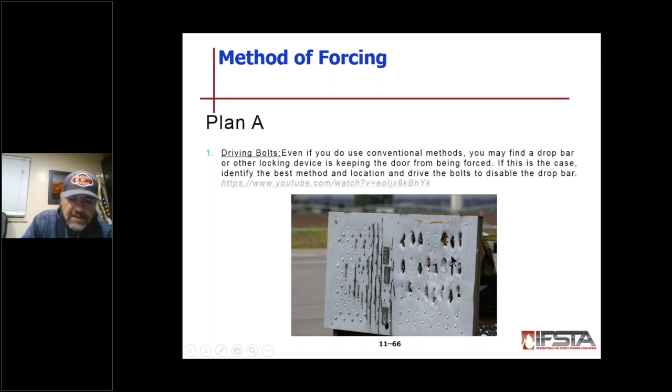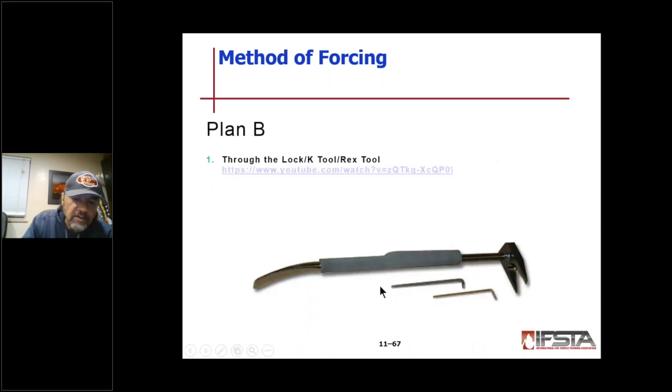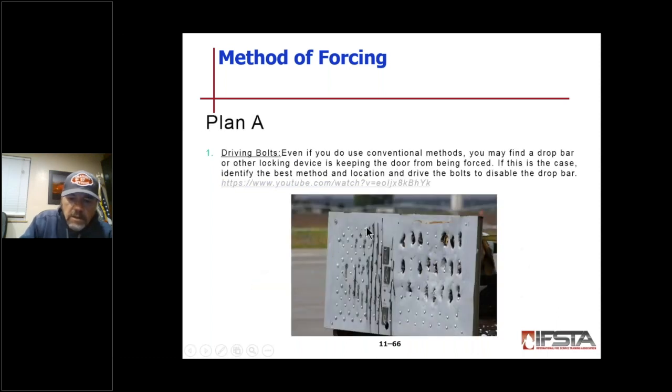If you're not able to do that, you can also take a rotary saw. On the left-hand side of this is where they've used the rotary saw to cut off the head of the bolt. Get the saw blade just in the gap on the edge of the carriage bolt and cut right through the carriage bolt head, or you can actually get in and slice through the door itself, going deep enough to cut through the bolt itself.